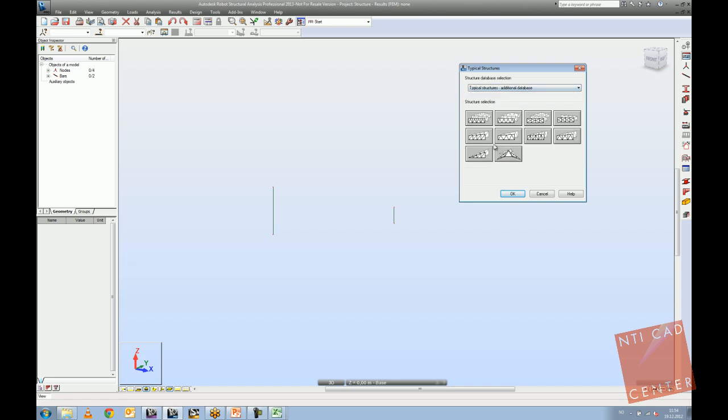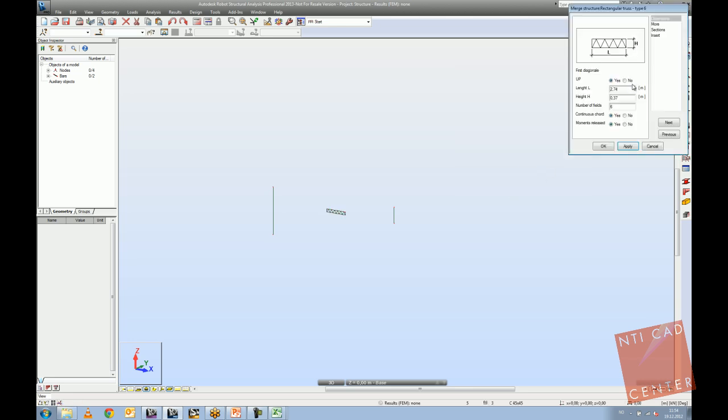So basically you can use this. In general, I use it just for trusses in a way. When you enter the dialog box here, you can specify which truss you want, and you see the sort of ghost images behind. So basically it means that you can achieve that kind of truss shape using this button. What you need to do is select the type of truss you want, click on OK, and then start specifying it.